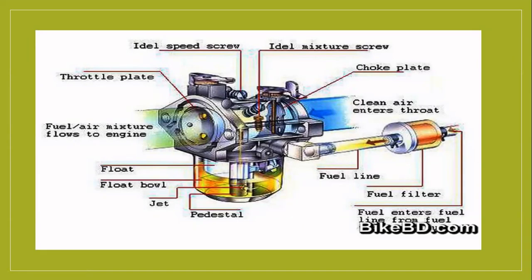Sometimes some engines, after start, take 1 or 2 minutes before you drive the vehicle because it has to be heated. That position is called idling. So this idling speed should not be too high so that the vehicle is stable. So you want to set that speed by the idling screw. Very carefully set the speed. You will set it yourself by screwdriver.